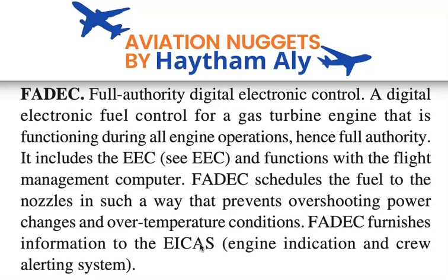These are the primary engine indications that must be sent directly by the FADEC. The engine also has secondary parameters like oil quantity, pressure or temperature, or vibration indications. These may not be sent directly by the FADEC, but will be sent through another computer or the interface concentrator, what is called the engine interface unit, or EIU.